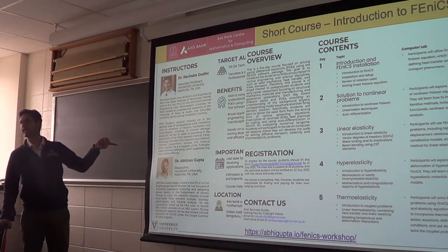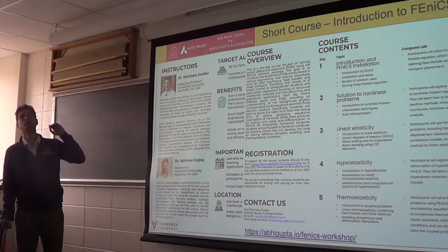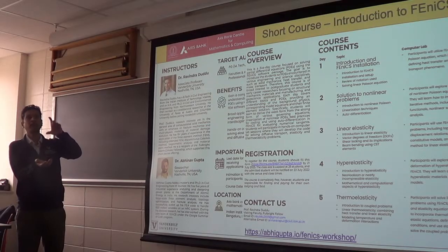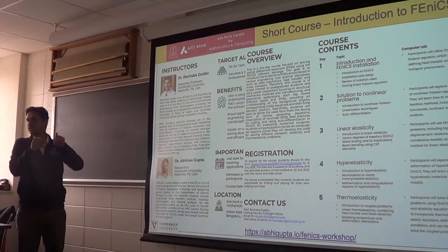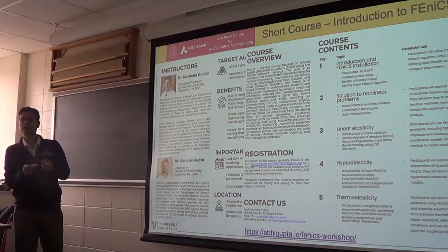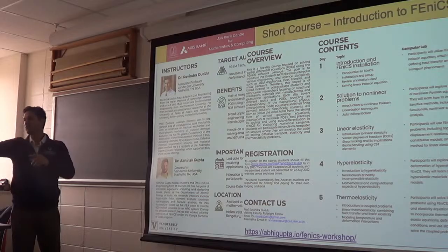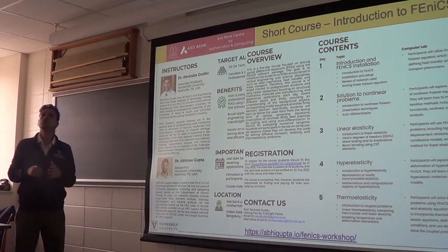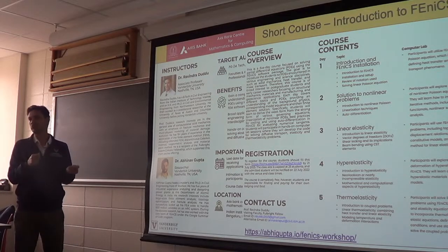Because this is quasi-static, we were looking at keeping the ratio constant. That means the height of the water divided by the depth of the crack. We call that ratio HS over DS. We were keeping that constant. So every time the crack propagated, we had to add a little bit more water to keep that ratio constant, and then we got those results for various cases, right? So the water level is changing in that.